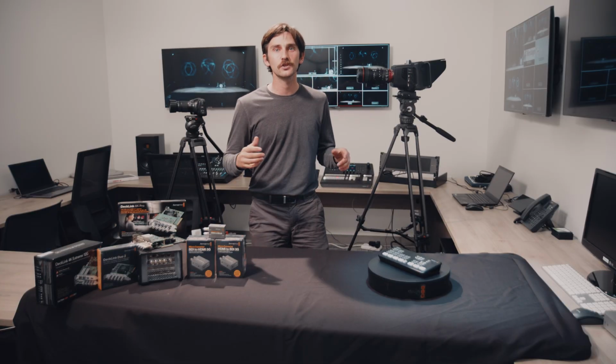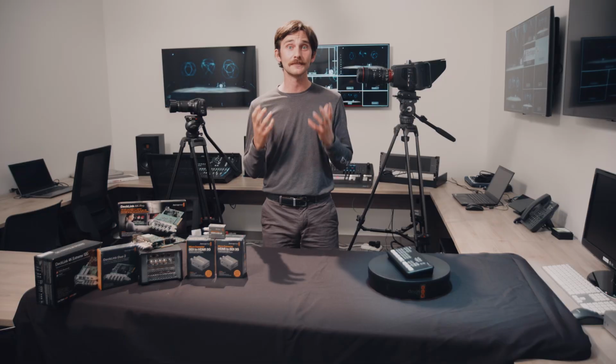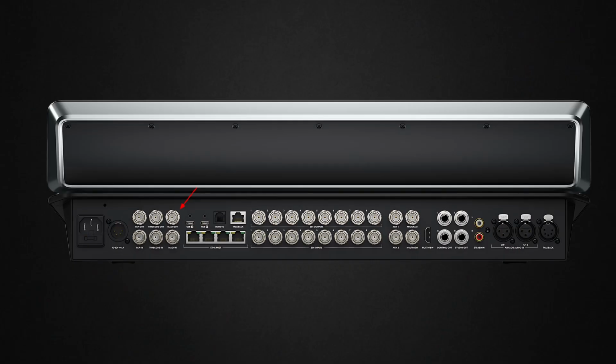The Television Studio units also function as substantial broadcast mixers with MADI digital audio in and out, dual XLR and quarter-inch TRS inputs, 5-pin XLR and a network jack, each for TalkBack comms input options, 2 USB-C connections for recording to an external drive, and lastly, for connectivity, the Television Studio has 4 10-gig network ports to function as a desktop switch as well.